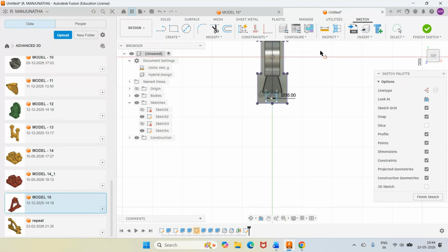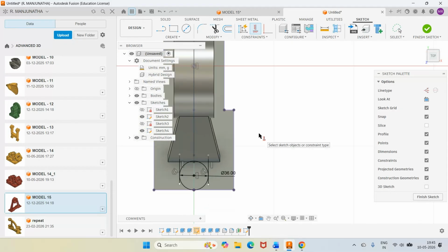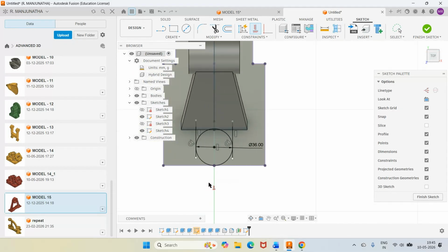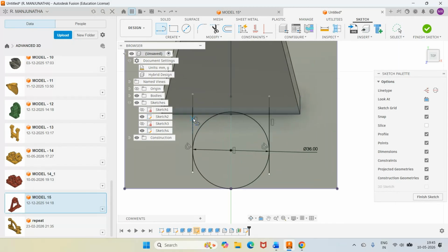So here I will go for vertical, select this point and vertical to this. Now this entire thing has been placed. Okay. Now I want to go for trim. Go to trim this point. Okay, sorry. I'll just press Control Z and go for line, select this line from this intersection where exactly that point is. Now I will take this endpoint to this endpoint, tangential to this.